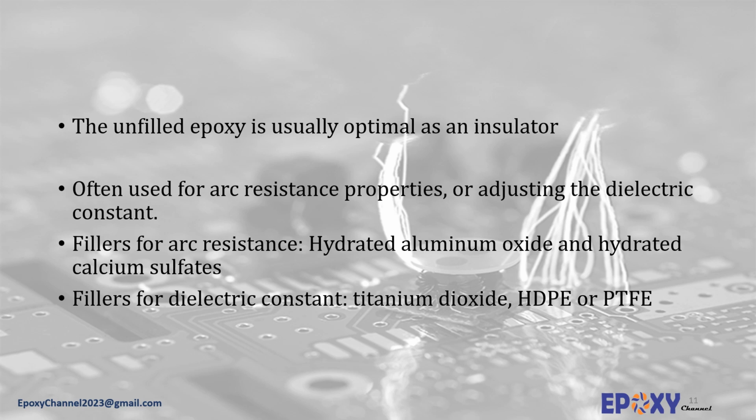However, the dielectric constant of epoxy adhesives can significantly be reduced by using fillers with low dielectric constant, generally polymers such as high-density polyethylene or PTFE. Hollow spheres containing air with a dielectric constant of 1 can be used as fillers to significantly reduce the dielectric constant of epoxy as well. By use of inorganic microballoons, dielectric constants as low as 1.5 have been reported at filler loading about 20%, compared to a dielectric constant of 4.4 for the unfilled epoxy system.